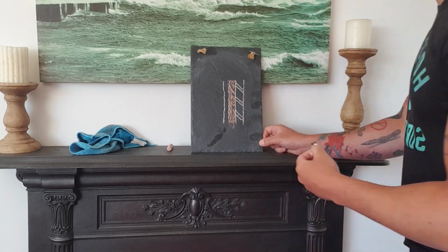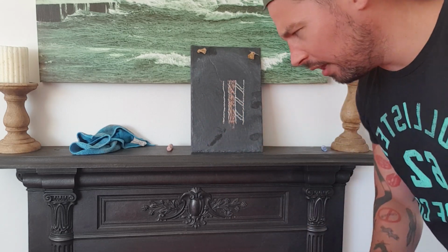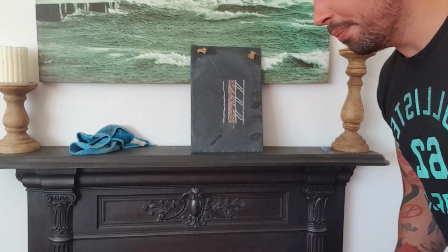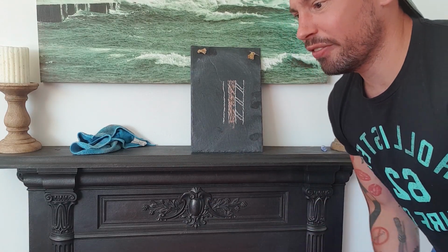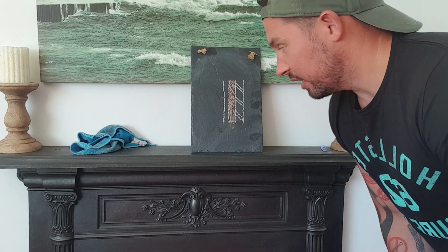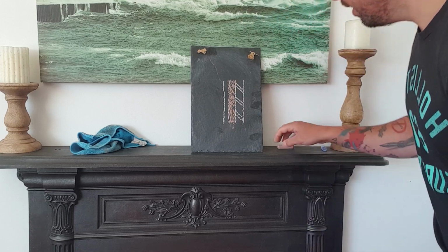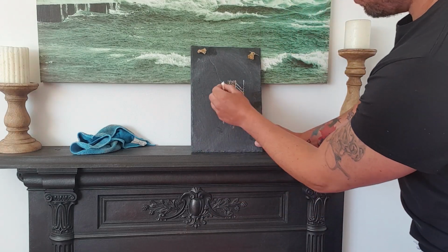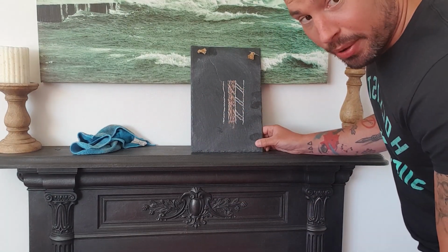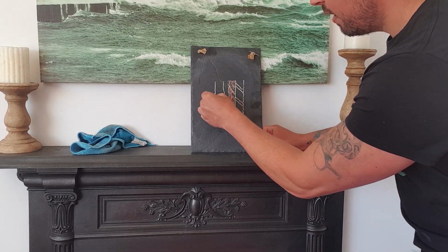Now, 50mm clear cavity is set out in Part L and Part C. In Part C, depending on the area where you live or where you're building, this cavity could be increased to stop excessive weather breaking into your wall and decreasing your insulation, etc. But go onto my blog, I talk about that in a bit more detail with Part C and Part L. And then, once we've got our minimum clear cavity of 50mm, we're going to have a finish of our choice.